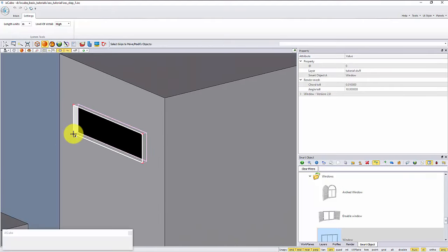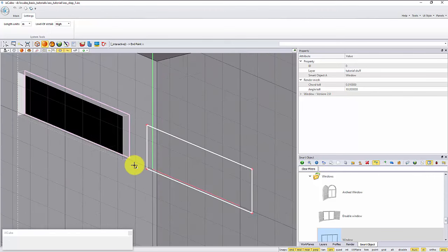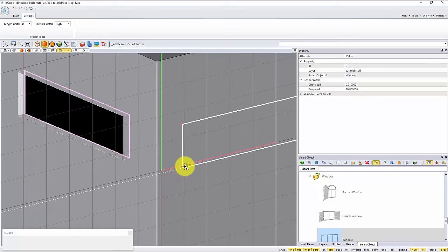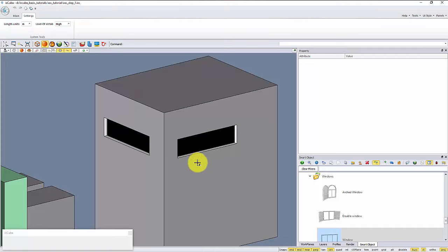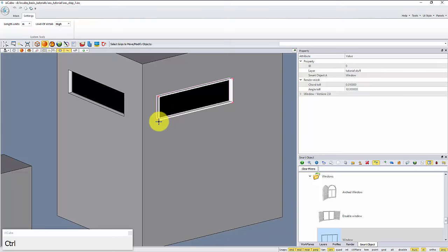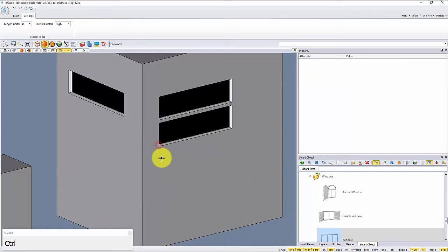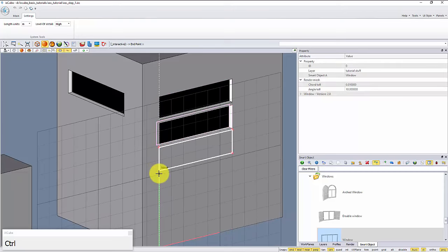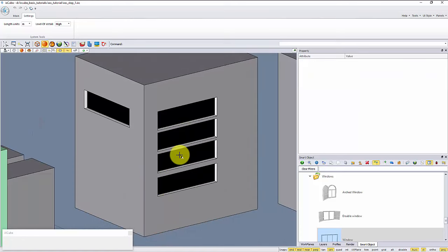So if I drag this object, this line is basically the baseline of the former window, and if we keep down the Control key and click, we clone, we make a copy of the window. So that's useful because I can just click on this one, keep down the Control key, and pull down this window like that, to make a series of copies.